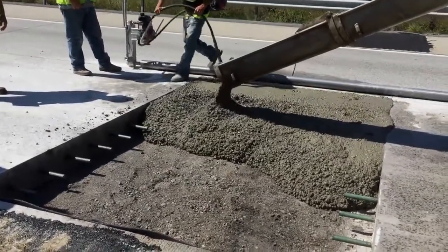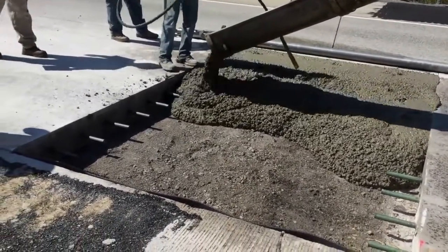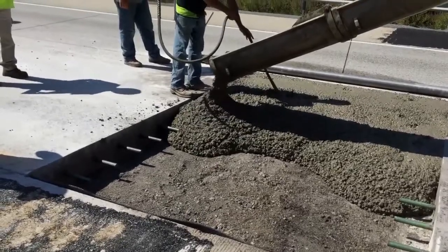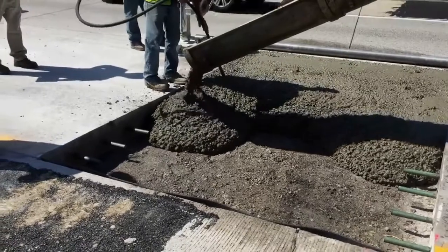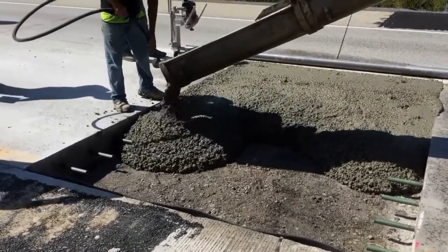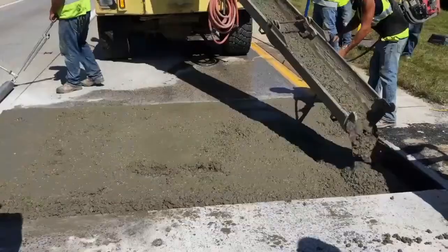Concrete materials. Normal strength concrete is Class AA paving concrete. It has a 7-day minimum compressive strength of 3,000 psi, a 28-day minimum compressive strength of 3,750 psi, and is not placed if ambient air temperature falls below 40 degrees.